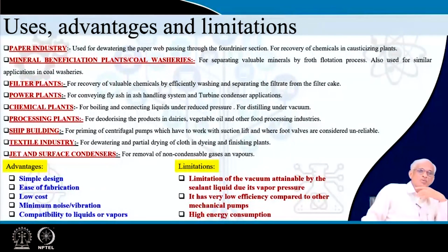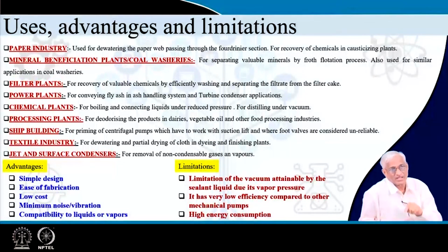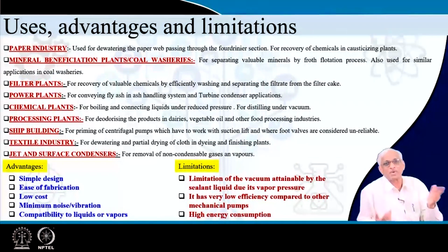Then there are of course compromises like using mineral oils and other things, and there are certain processes where the loads may not be that sensitive to the chemical composition or whatever impurity effects that liquid ring itself will contribute, then you can use other liquids. And if the vapor pressure of that liquid at that temperature is less, you will get better vacuum.